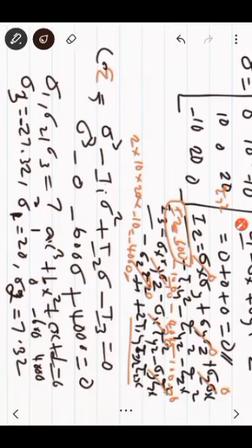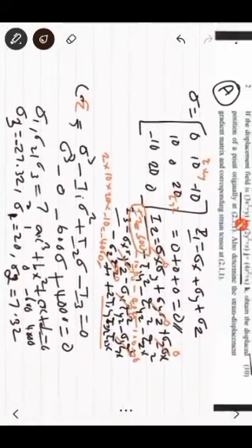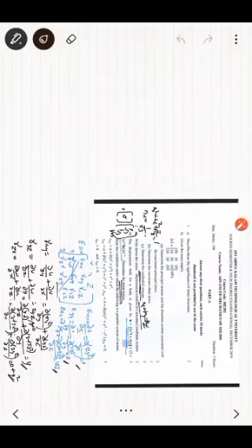The least value is sigma 3, so least value is minus 27.32. So now if we want to check, you can check whether sigma 1, sigma 2, sigma 3, you add this, you get equal to 0. What is I1? I1 is 0. That's all. So add sigma 1 plus sigma 2 plus sigma 3 and equate it to 0. I have written here.